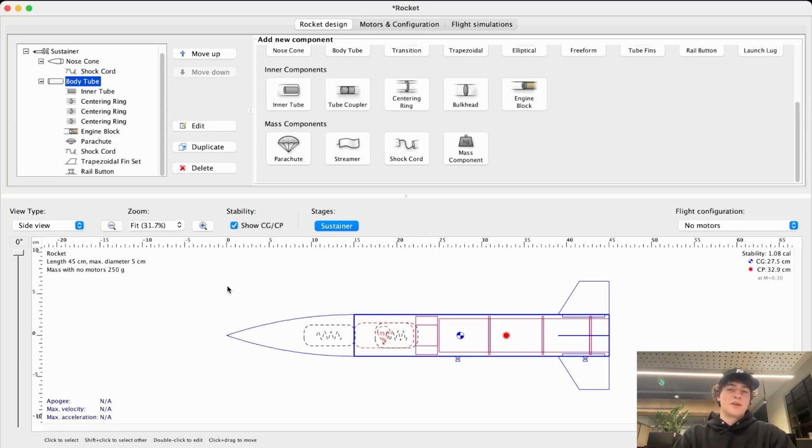It's going to have an outer diameter pretty much equal to the inner diameter of your body tubes. It's literally going to be this tube that they both slot onto to hold them together. So very, very important element when building bigger rockets. Probably not going to be used in our L1s because, again, our nose cone is going to have that shoulder that's going to allow it to slot into the body tube very similarly.